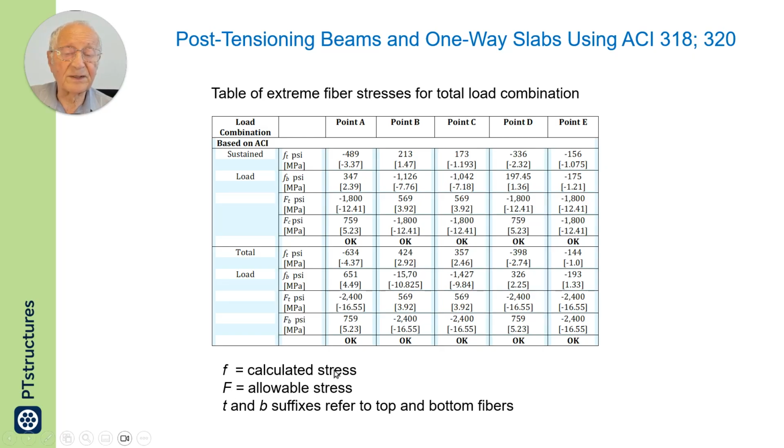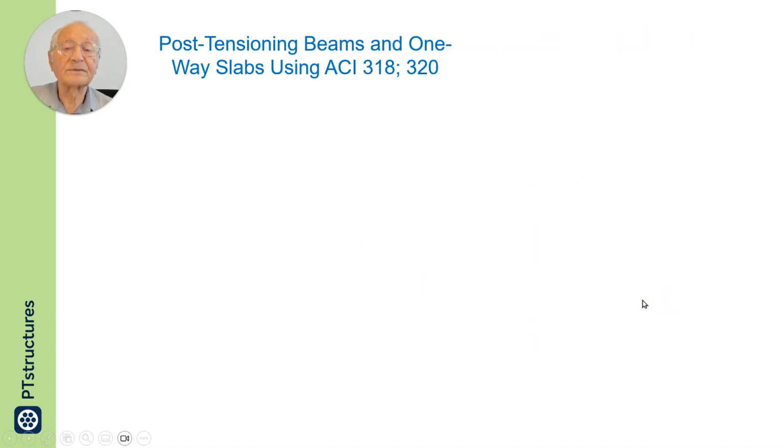The calculated stress, the allowable stress, and we see whether the calculated is within the allowable at points that I have selected along the member, at the face of the support and at midspan, and they all seem okay based on the sustained and total load that I have.